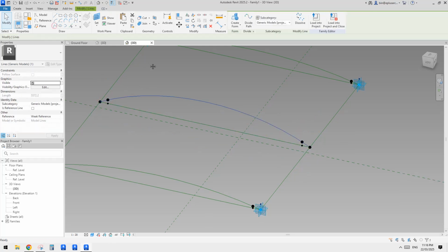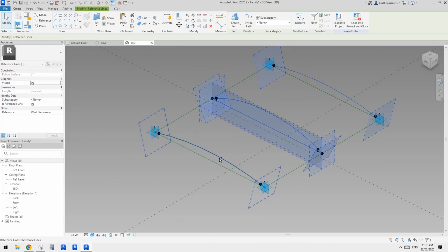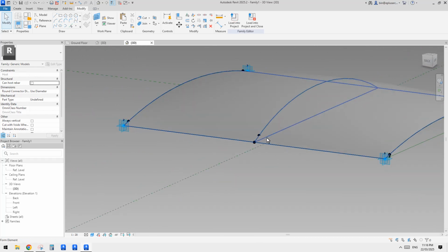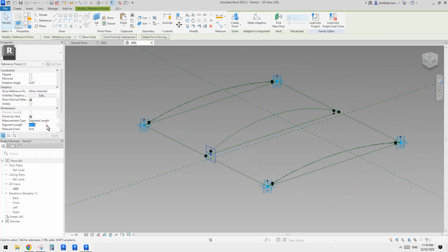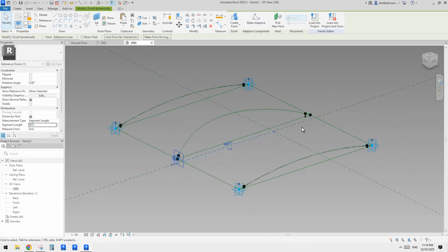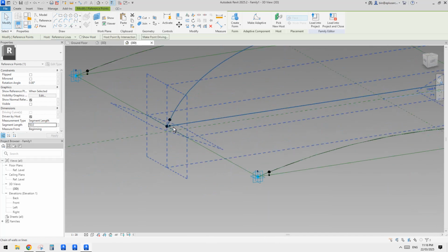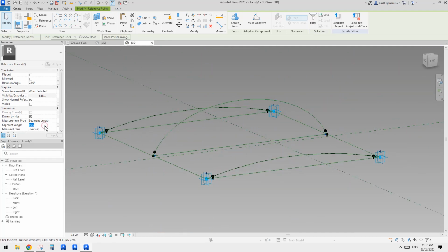spline first, so we can always even create the shape form, right? So this is it, and then we can go back. I'll just type WF so we can pick the point. So reduce this one. For example, I'll change it to 50. You will see it change the look of this. So when the number becomes smaller, it goes higher here.